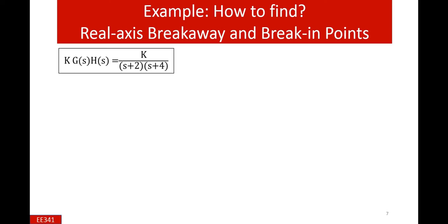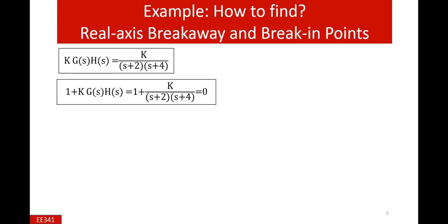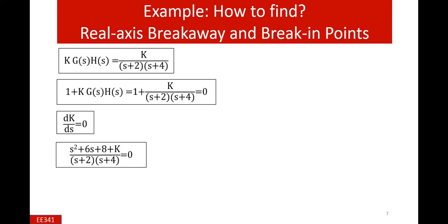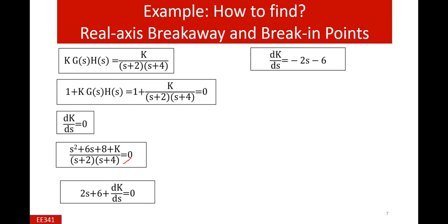When the open loop transfer function is given, we have the characteristic equation from the closed loop transfer function, which is the denominator part. By taking the first derivative of k with respect to s, when s is on the real axis, we can find the value of k. By taking the LCM in these equations and taking the first derivative, the denominator part becomes 0 after multiplication, and dk/ds at that point is 0, because this is the maximum value of k.